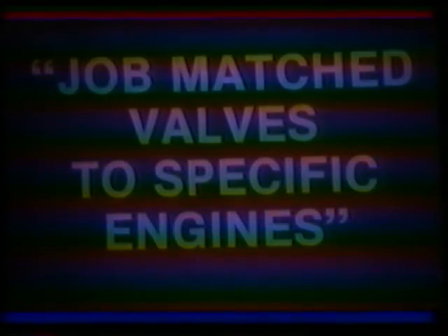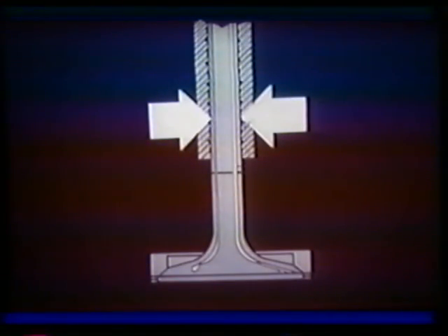The valve stem moves up and down in the valve guide, and a close fit is necessary to minimize gas and/or oil leakage. Valve guides are precision bored from graphitic gray iron. The flakes of graphite in this type of gray iron assist in self-lubrication of the contact surfaces. Most Caterpillar valve guides are threaded.